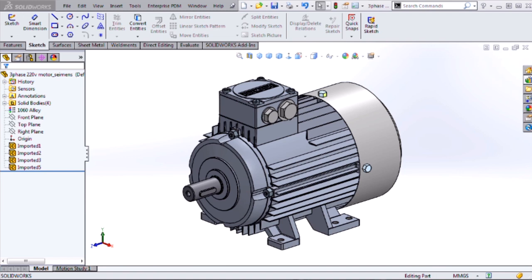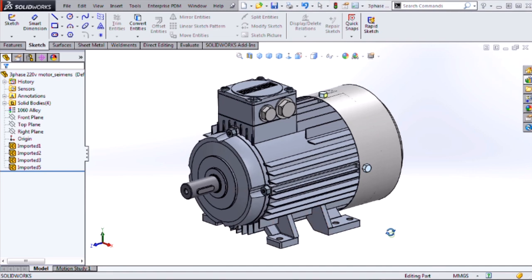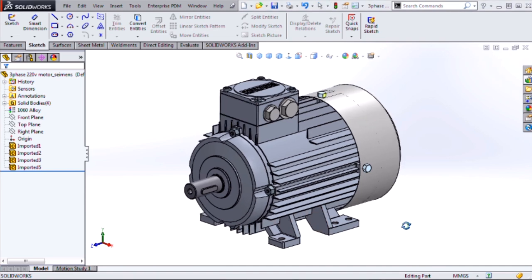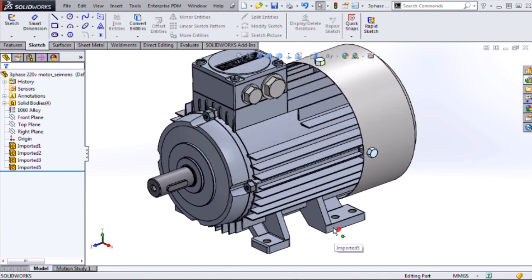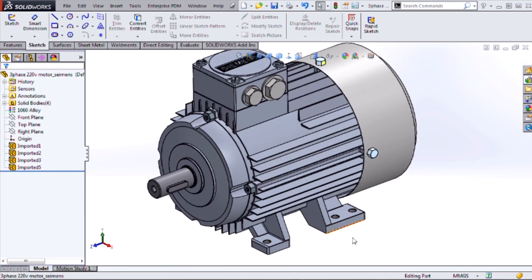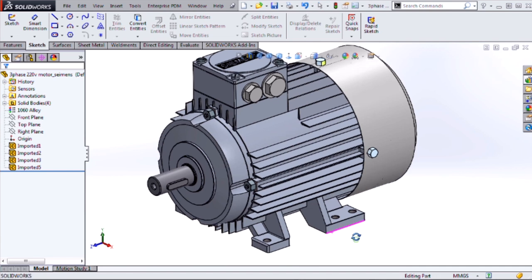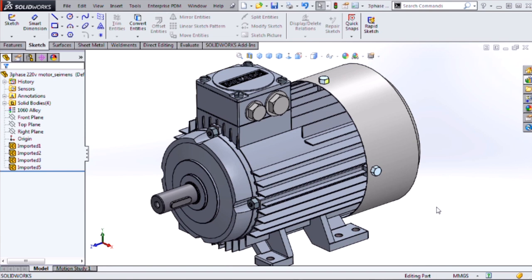And in this blog, I'll cover the basics of creating smart components in SolidWorks for SolidWorks Electrical 3D users. And while I'm gearing it towards Electrical 3D users, this information is useful for any user of SolidWorks that wants to speed up assembly creation. For those of you that are not familiar with this functionality, it's a way to associate components and features with a component that you want to drop into an assembly, such as mounting holes and fasteners for this motor. And when we set it up as a smart feature, it will create those mounting holes and add those fasteners for us automatically. Great time saver.